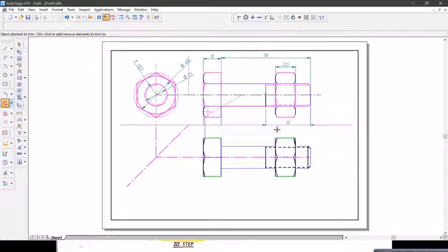So now this completes 3 views of hexagonal headed bolt nut assembly. Now if you want to add a washer, you can place washer in touch with either a nut or in touch with a bolt head, not somewhere. Now what is the diameter? Diameter is 2d plus 3 mm you can take, or 1.5 mm you can take.